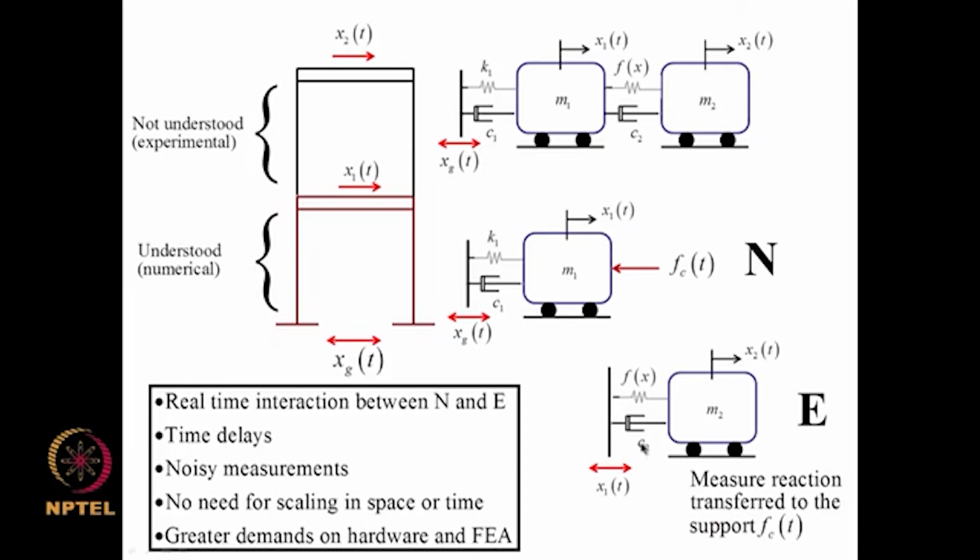We apply this displacement, maybe on a shake table in real time now, it is not pseudo dynamic, I mean it is not static, and we measure the reaction transferred to the supports on our shake table or reaction wall, and that is transferred to the numerical model. So the integration of the equation of motion and dynamic testing of the experimental component take place hand in hand in real time. So a 30-second event is